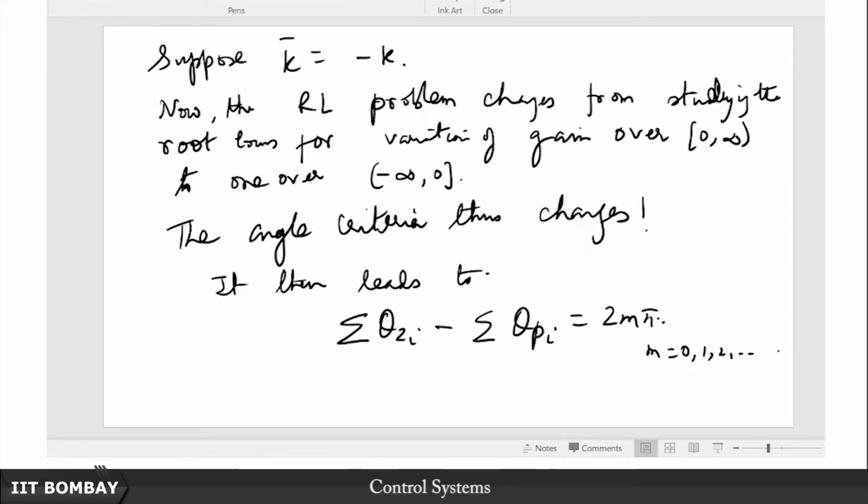So, in some textbooks you will find that this root locus is called complementary root locus. In other textbooks you might find this called the 0 root locus. So, remember they call the conventional root locus as the 180 degree root locus because it was an odd multiple of 180 degrees pi, and this one is basically a multiple of 0 degrees or modulo 2 pi.